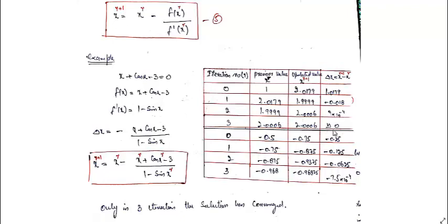So here you can see delta x has reached close to 0. It's a very small value, but I have calculated it to be equal to 0. You can see that this is slightly faster as compared to the Gauss-Seidel method. It is converging in fewer iterations. Here in only 3 iterations, the solution has almost converged.